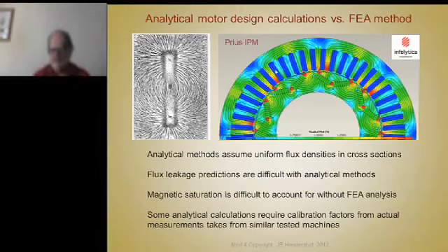In other words, if I know that this magnet has 100,000 lines of flux, and I know that flux from that magnet has to go across this cross-section, I divide this area into the total number of lines to get lines per square inch or lines per square millimeter, whatever the case is, and I assume that it's uniform across there, but it isn't uniform across there.